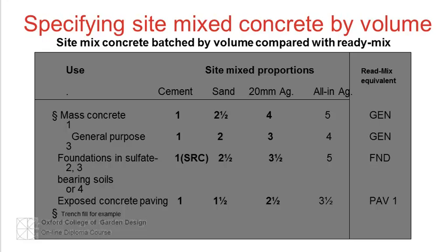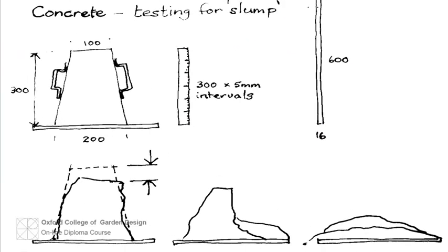Normal concrete is consolidated by manual tamping, board or mechanical vibrating poker or a vibrating beam. Workability is the word used to describe the ease with which concrete can be spread, levelled and consolidated.